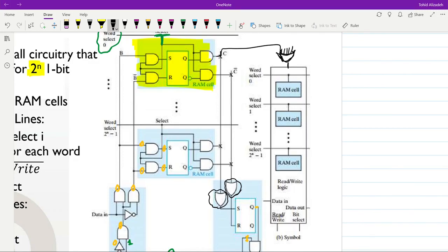So what you see here basically is the same as what we have here. Each input is connected to the C output of the cells, and just to simplify the representation, we just place an X between the line which is connected to the OR gate and the C output of the cells.